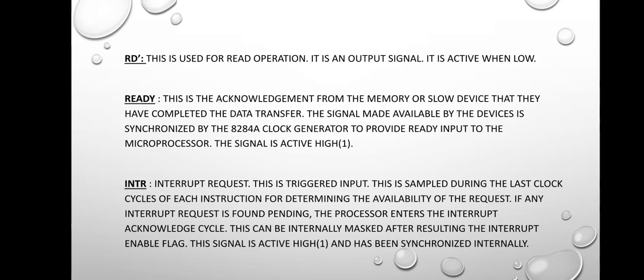And READY. This is the acknowledgement from the memory or slow device that they have completed the data transfer. The signal made available by the devices is synchronized by the 8284A clock generator to provide the ready input to the microprocessor. The signal is active high.